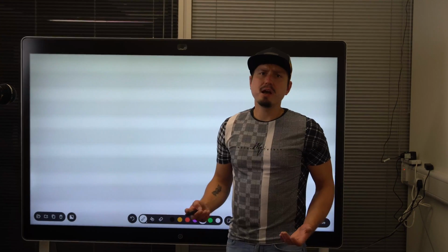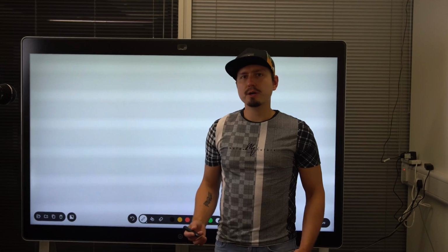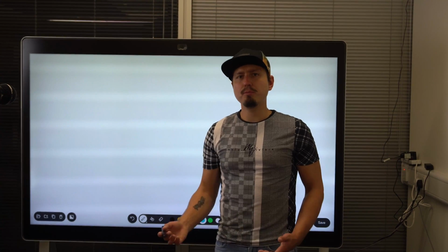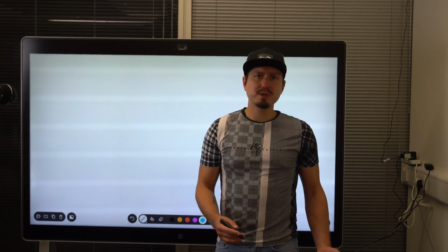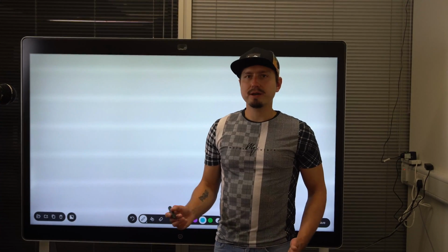So finally, after I've completed the PCB layout, I will also think about all external connections made to and from this PCB, which may be made via USB cables or XLR cables and stuff like that. If this is a USB cable, is it 360 degrees shielded?